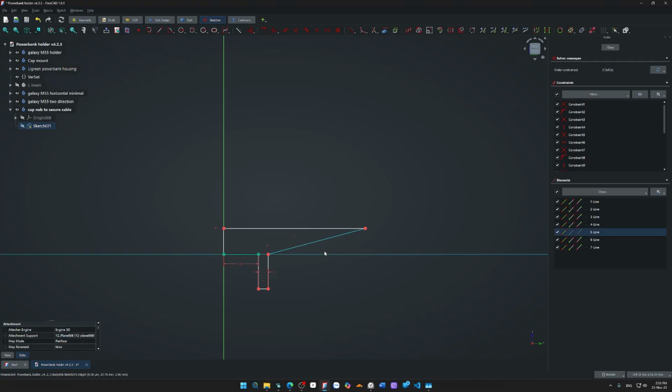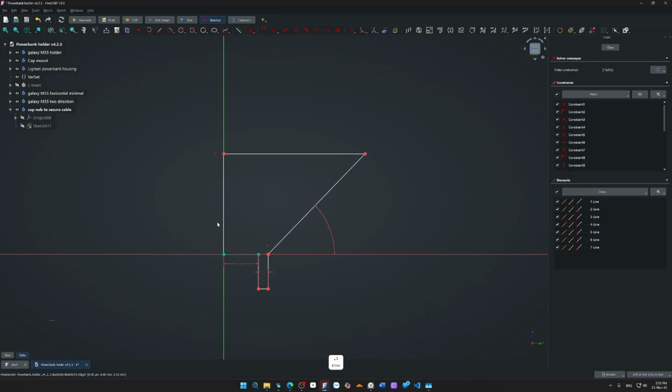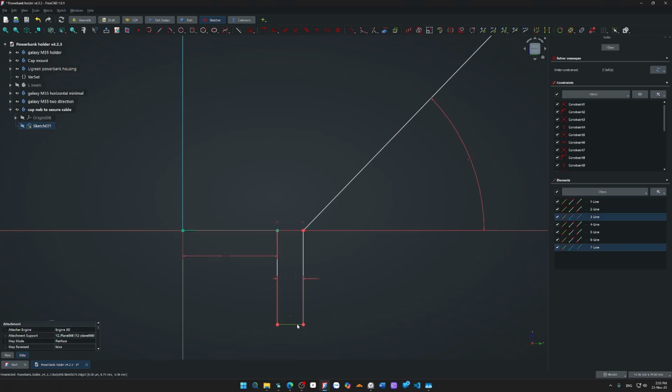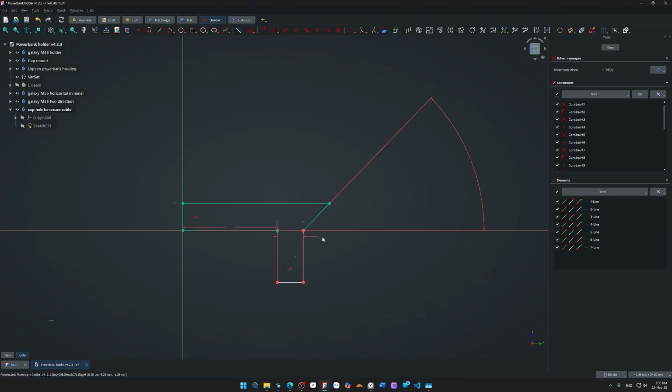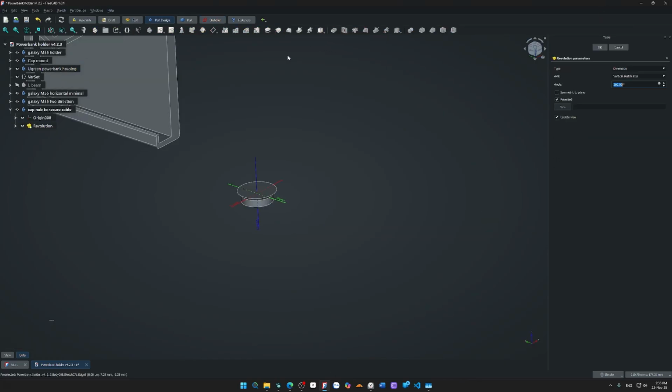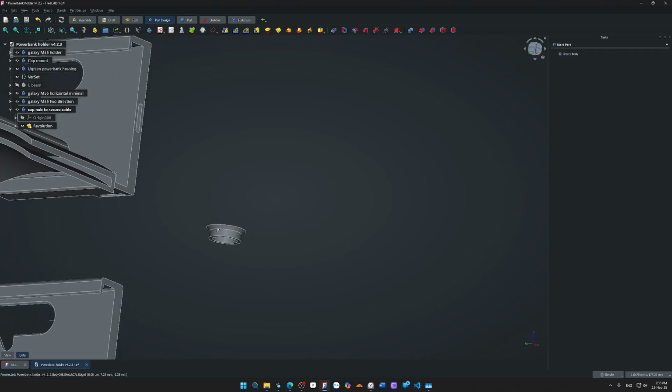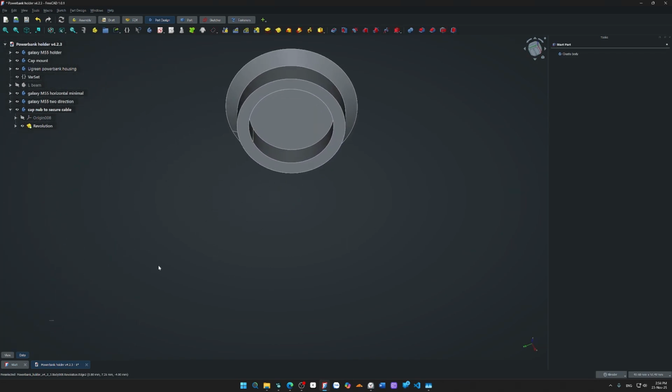Two millimeter walls, 45 degree. So I'm setting the walls, so make them equal. Now the length of this thing, I forgot the length of the pad. Gonna have to measure it again. No, it is actually just 4 millimeter. Check. Yep, 4 millimeter. Give it 360. Boom. Got the same thing. Nice.